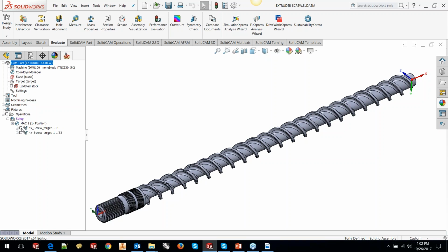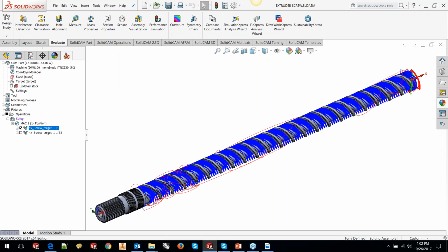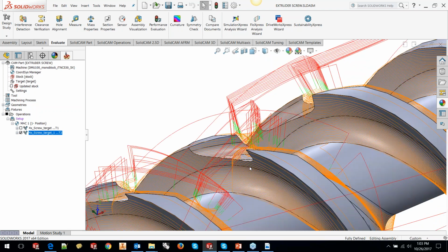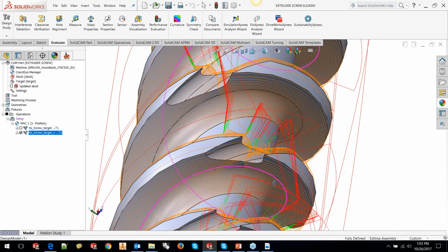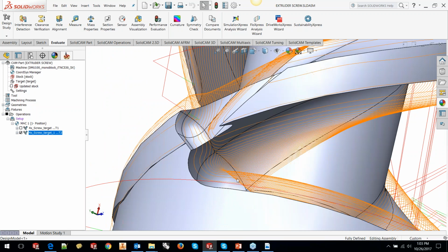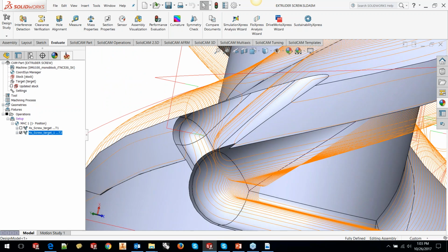So the roughing with 25 R5 took 22 minutes to calculate, and it has done every area perfectly. Okay, the same one, finishing, took about 30 minutes to calculate. Okay, now you're seeing a lot of retracts because it's treating the regions separately. It's machining, for example, even if I go to the end, it's done a pretty neat job out here. Okay, this is something that's really unimaginable in our generic 5-axis.